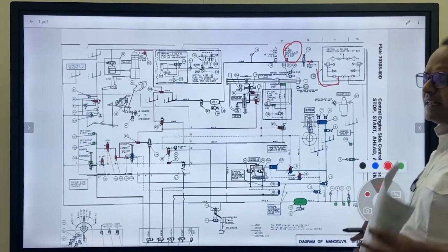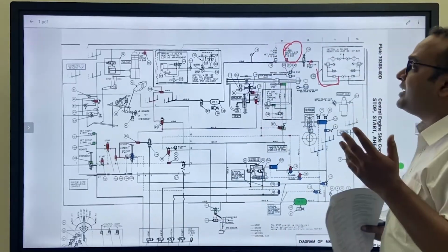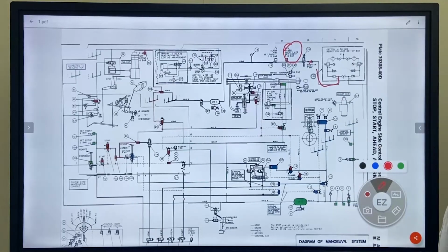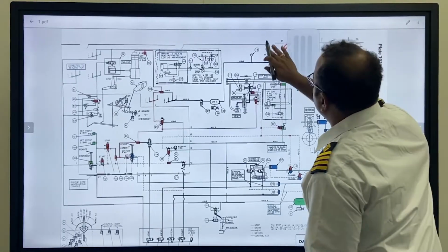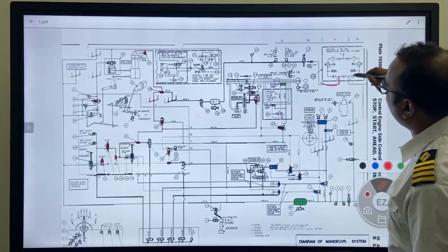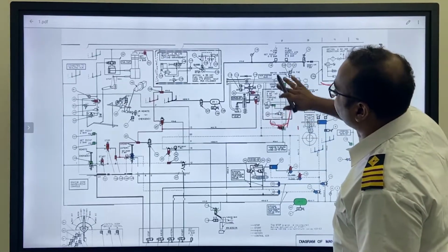More or less it is the same. You should not bother about these values. The range should be bound between 6 to 7 bar or 7.5 bar. Fine. So one thing is clear, your air is now ready. 30 bar came and divided into two parts, safety air and control air. Fair enough? Very nice.